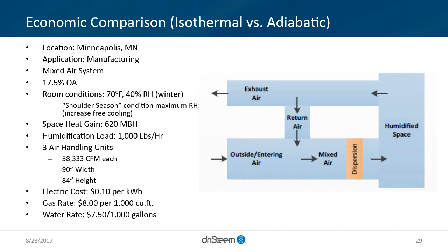So really the things that we're looking at, the top 2 lines are utility costs, but looking down to the 3rd line, talking about annual gas preheat cost. In this specific example, we do need to heat the air for these winter months. It's roughly $10,000 more, $11,000. But what we gain is the cooling savings from offsetting mechanical cooling.